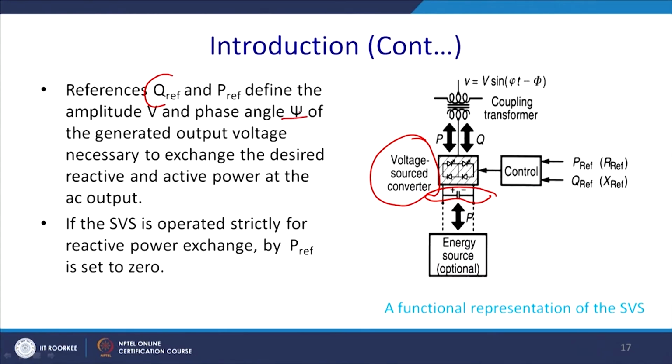So, the reference Q ref and P ref define the amplitude V and the phase angle, and the output voltage is generated, necessary to exchange the desired reactive and active power at the AC output. So, if the SSSC is operated strictly for reactive power exchange by setting P ref equal to 0, that means you do not require any storage element.